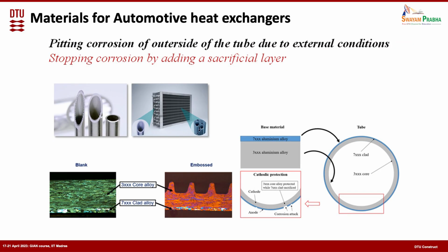Just to show you another integrated design, we were talking about the sacrificial anode, which you are very familiar with, because zinc coated objects are seen everywhere. That is the principle of cathodic protection, using a sacrificial material for the steels. Let me give you another example of thinner structures.